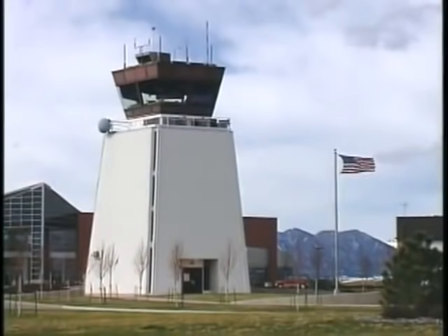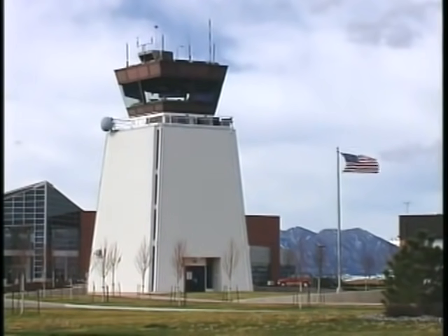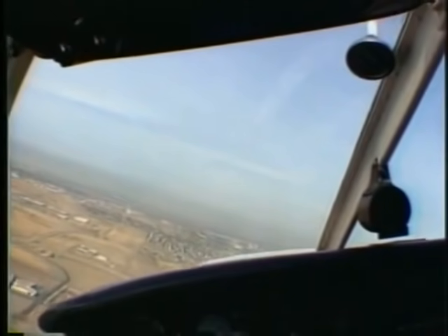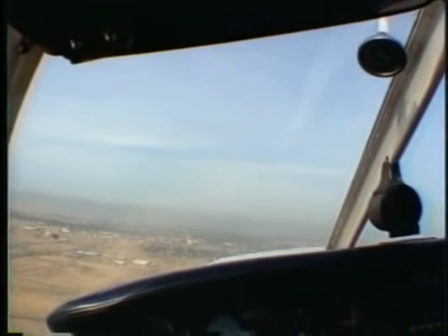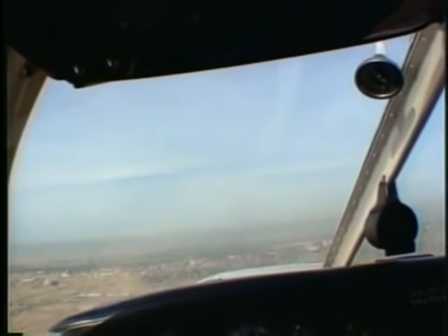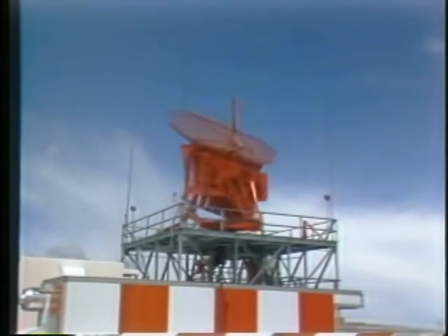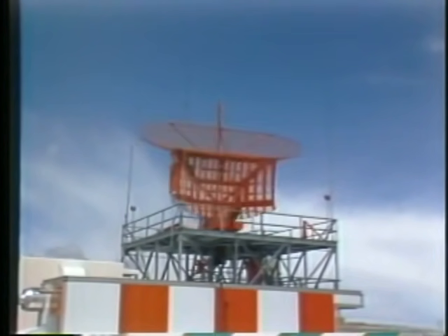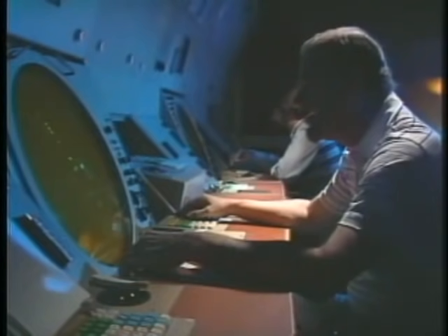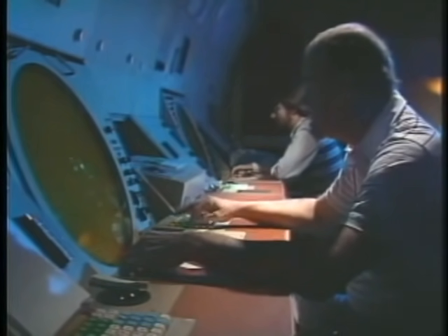The control tower operates in much the same way for IFR flights as it does for VFR flights. However, for IFR flights, the tower controller will hand you off to departure control when you're about a half-mile beyond the runway end. Departure and approach control provide IFR separation and handling during the departure and arrival phases of the flight. In metropolitan areas, a single radar facility often handles aircraft operating to or from several nearby airports. They also work closely with the en route center and the tower to transition air traffic smoothly between the terminal and en route airspace structures.